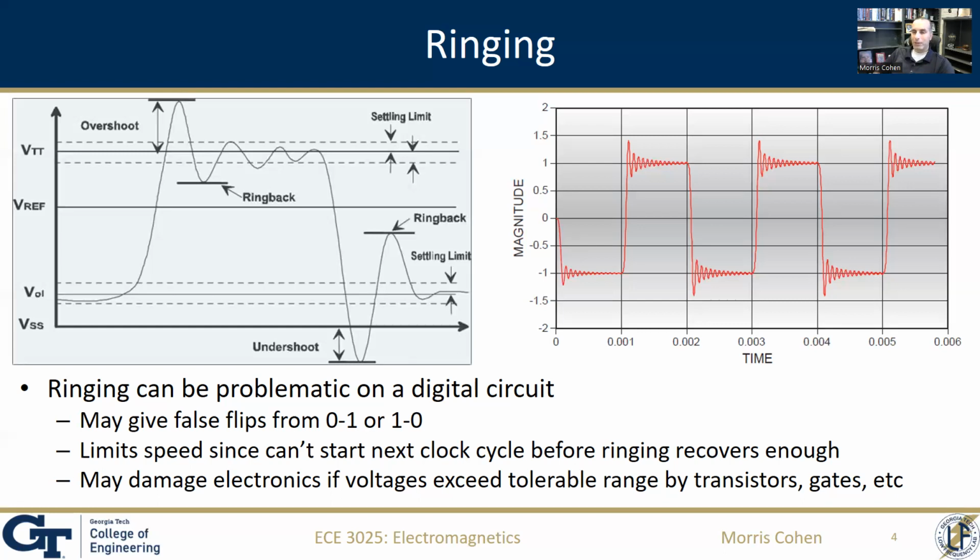This also is going to limit the speed of everything, since in principle, we've got to wait for this ringing to settle out enough before we can move on to the next clock cycle, the next bit flip. And if the ringing is too severe, we may have to wait too long, and that's going to slow down our speed.